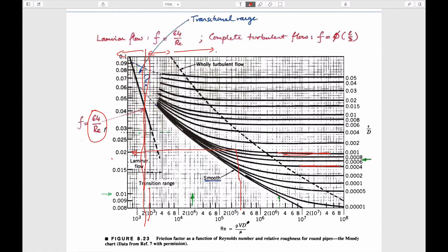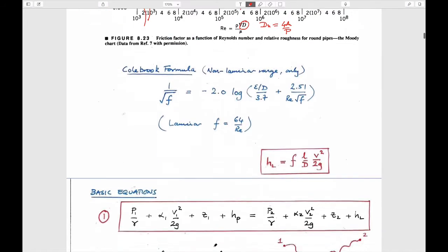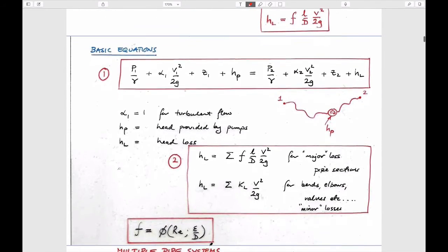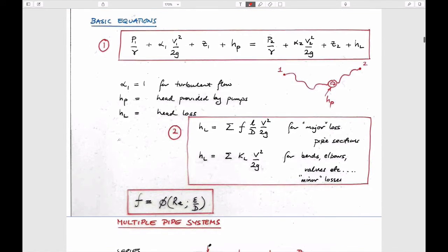The Reynolds number is always given in terms of a characteristic diameter, and for us that characteristic diameter is the hydraulic diameter, which we can calculate from 4 times the area divided by the perimeter, should we have such a geometry to deal with. Okay, so I think we've dealt with that before. We've talked about the energy equation,